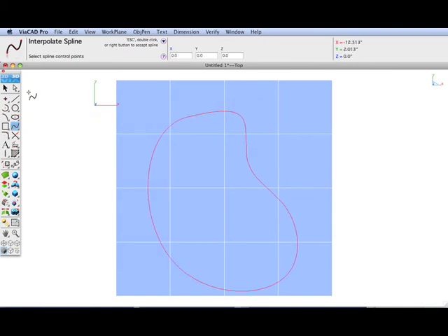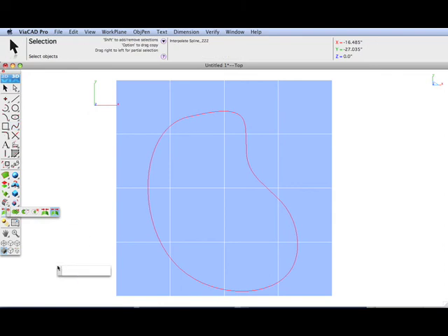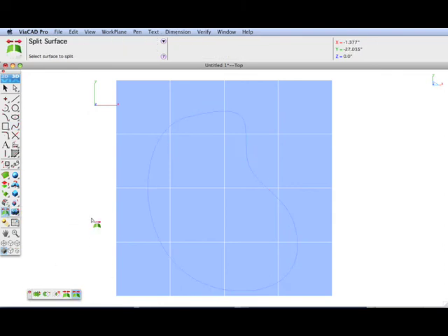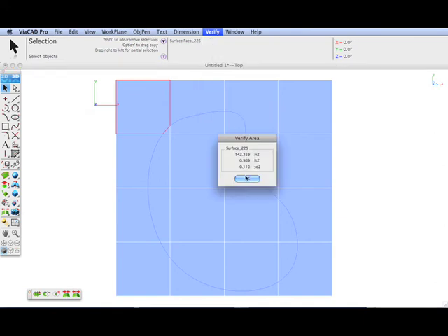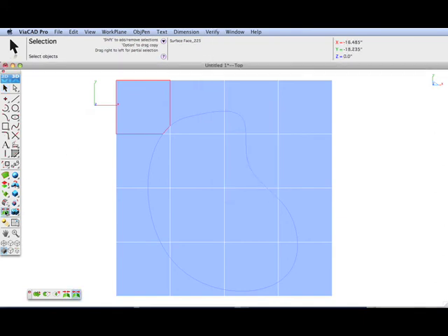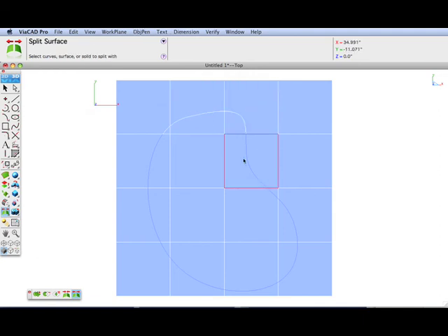Very good. And then we'll go ahead and move to our trim tool located in the advanced surfacing palette, and we'll select the surface and the curved trim tool. And what you can see now is we've actually trimmed that surface to that line, which has its distinct area. And let's go ahead and duplicate that command to each of these squares that our outline goes through.